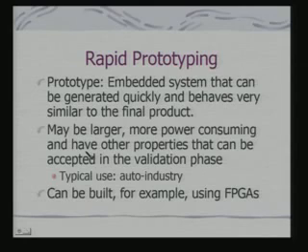If it is providing the navigation, the next part of the engineering aspect of the design is reducing its size, trying to optimize for the power, etc. And in many cases, these prototypes are built using FPGAs, because FPGAs can be very easily synthesized starting from, say, VHDL or SystemC descriptions of the embedded appliance.